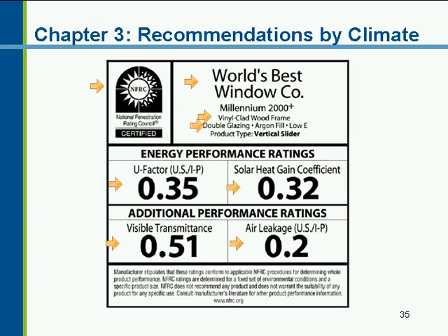If you're trying to refine your design, and if you're thinking about daylighting, you want the visible transmittance to always be higher than the solar heat gain coefficient. If you look at bronze glass or some of the mirror-coated glasses, you find the visible transmittance is low and you have more of a gloomy space.